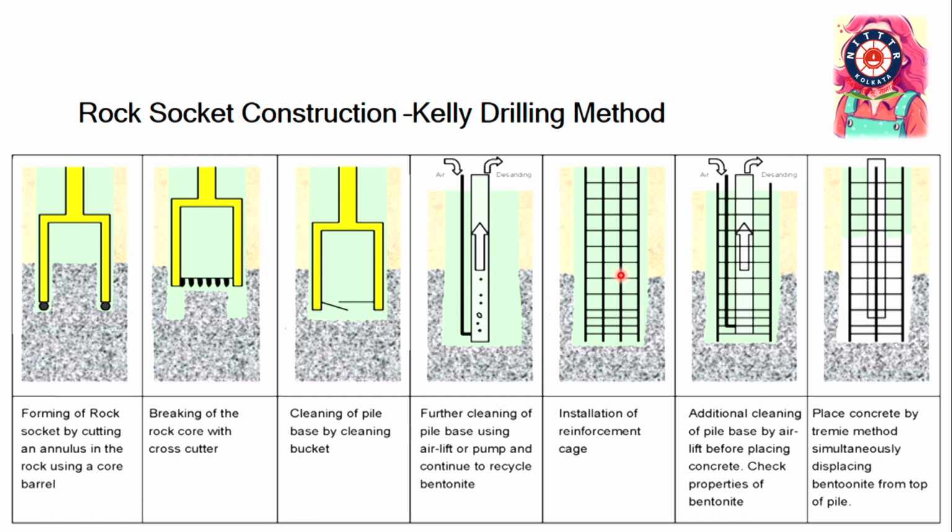Then you lower the reinforcement. Once you lower the reinforcement, some soil particles will again collapse, so for that purpose you should remove them by cleaning the borehole again. Then you have to do the concreting by the tremie method.